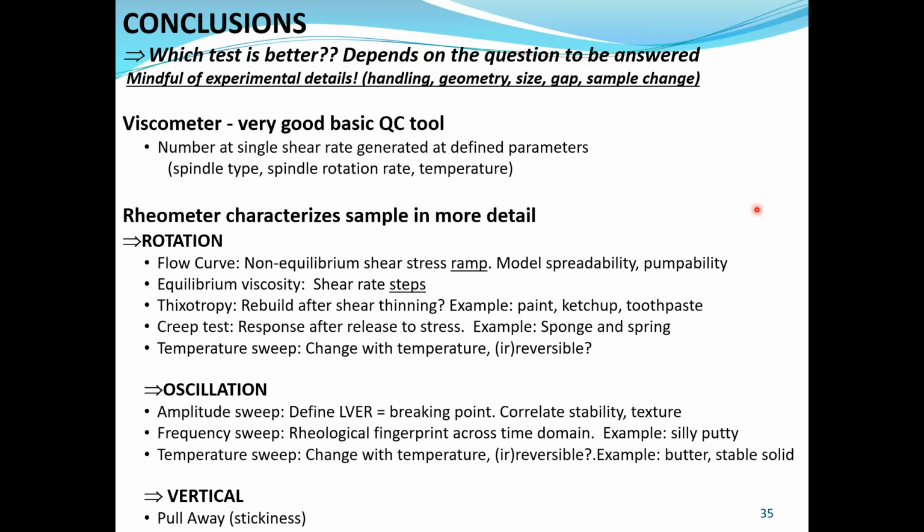We looked at equilibrium viscosity, shear rate steps. We looked at the rebuilding or catch-up of viscosity after shear thinning. The creep test is the response after release of stress. Is it coming back to its same rheological properties? An example of that was the sponge and spring, as well as the temperature sweep.